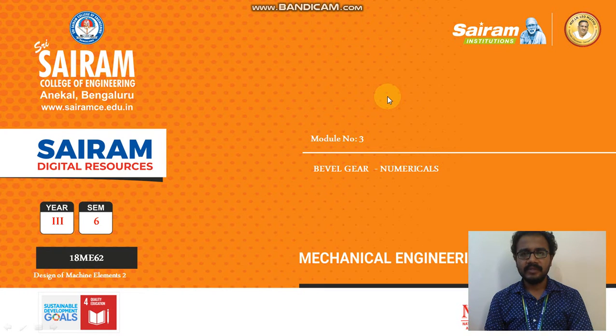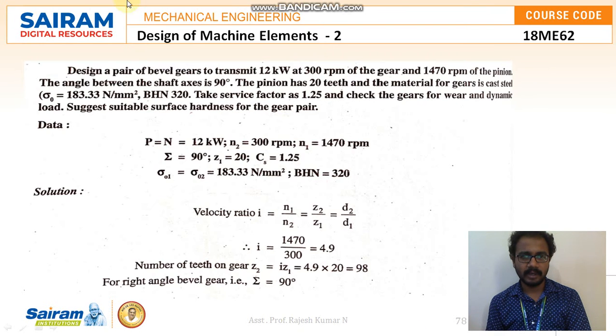Hello everyone. In this video, we will be discussing one numerical, that is a design of the bevel gear. Already in video 5, we had discussed one bevel gear problem, where we couldn't discuss in detail, particularly the last step, that is based on the dynamic wear and the strength. So in this problem we will discuss that in detail, and the previous steps, that is identifying the weaker member, finding out the tangential force and checking the stresses, everything remains the same here, so we will rush through them quickly, and the last step we will focus on more in this particular problem.